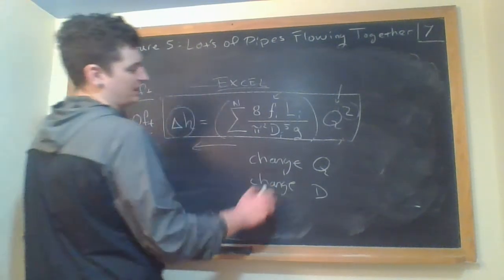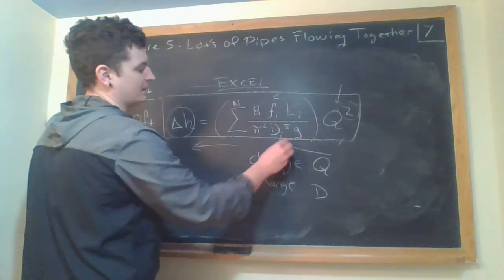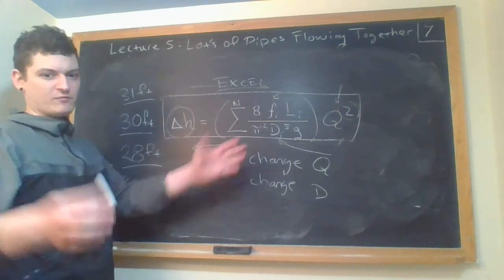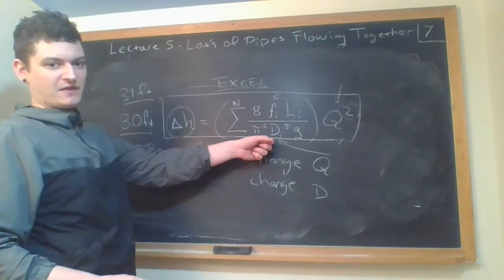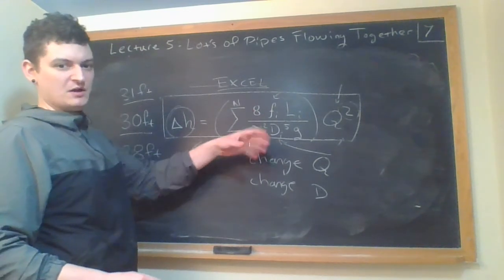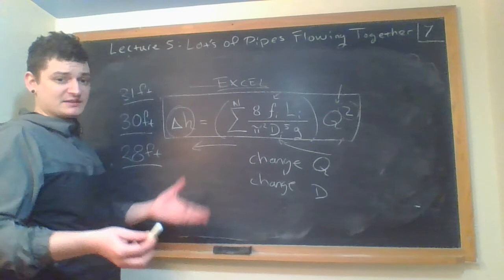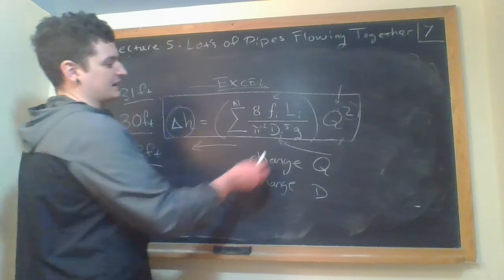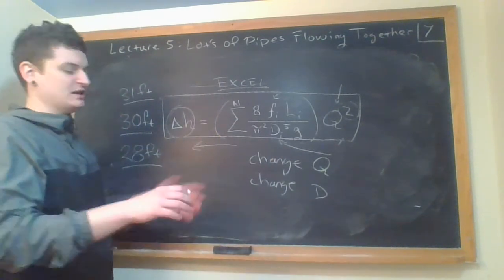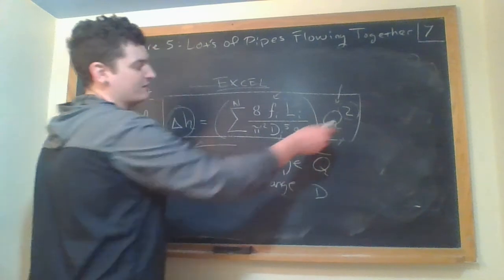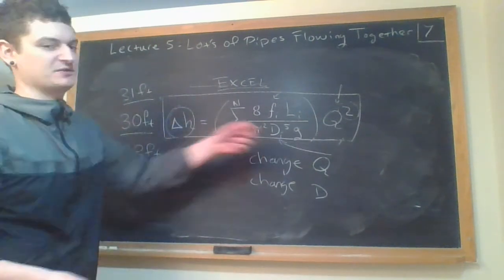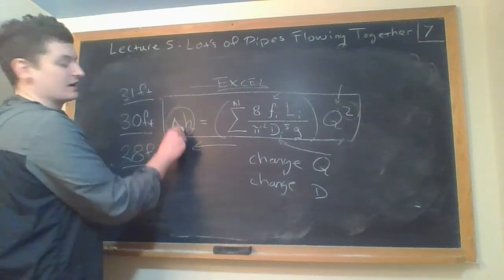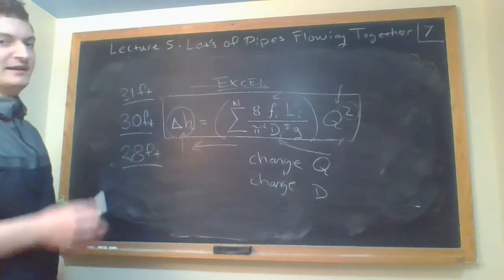And in fact, I do want to point out that Connor had a great idea where, in the end, you're kind of restricted on what diameter pipes you can use because there's Schedule 40 and all those are picked. So his method is he just had a Python program search through ones that would make this work, which I think is a really good idea because the solvers I have just give me the actual specific point values for the diameters. I like the idea of just searching through the Schedule 40s. It's the same idea: you're just really trying to get close enough to what the requirement is.